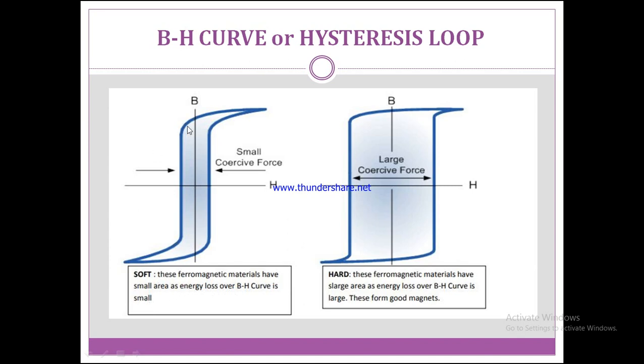If the area of energy loss is small, the BH curve also has a smaller coercive force, and we define that material as soft magnetic material.